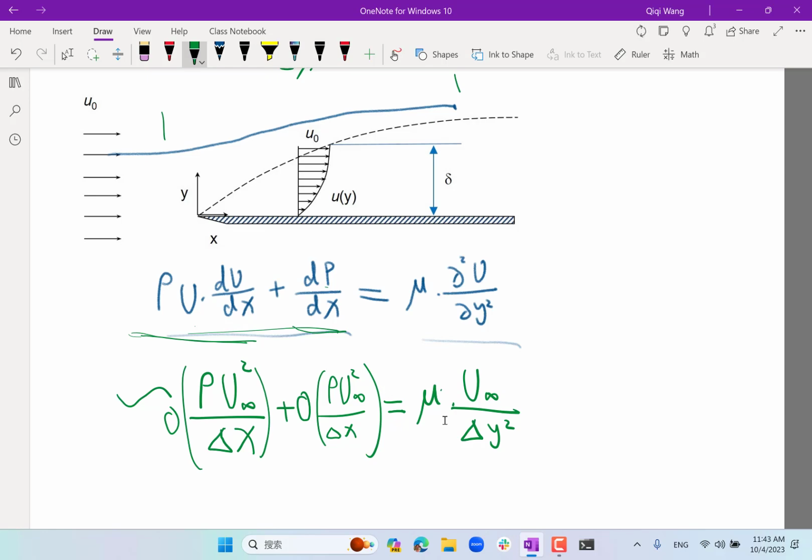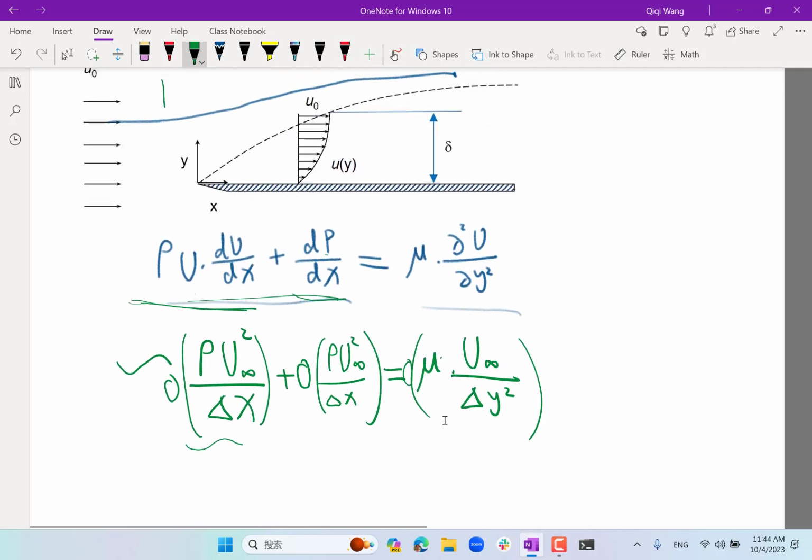On the other hand, if the right-hand side has an order of magnitude close to the individual terms on the left-hand side, then we can no longer say that the left-hand side adds to approximately 0 and use Bernoulli's anymore. So the relative magnitude tells me how approximately true Bernoulli's equation is going to be.